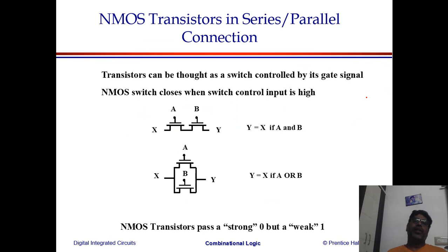The next comes the pass transistor. Yes, the previous logic, static CMOS logic, whatever we have seen is very good with respect to noise margin, stability, robustness. But one of the worst problems with static CMOS is it requires 2n number of transistors, which is actually more area consuming, connectivity consuming, and thereby more amount of capacitance.